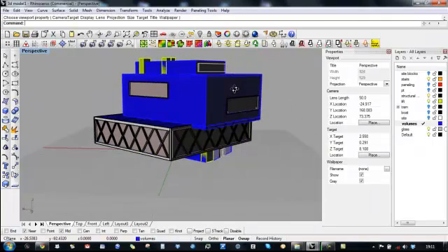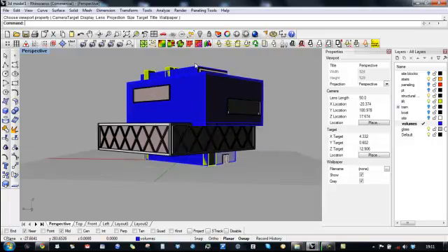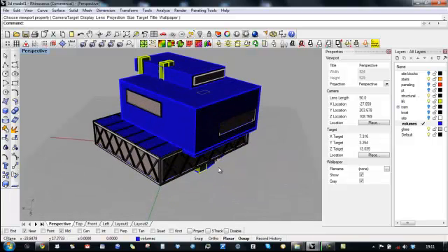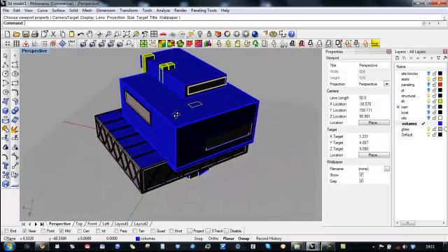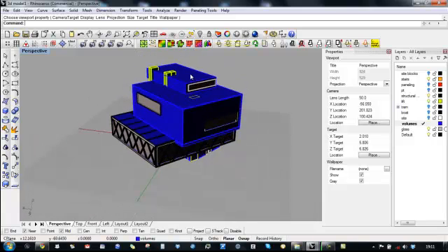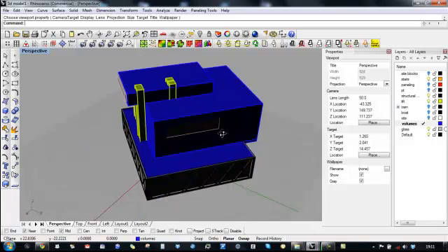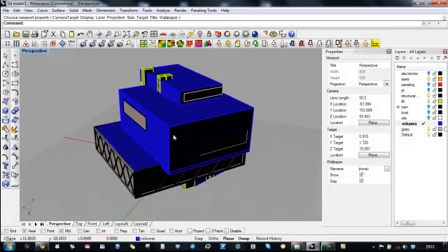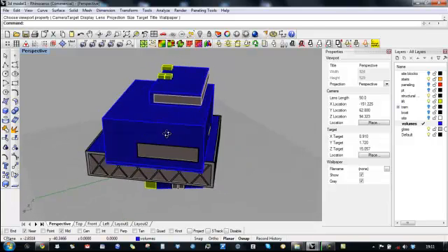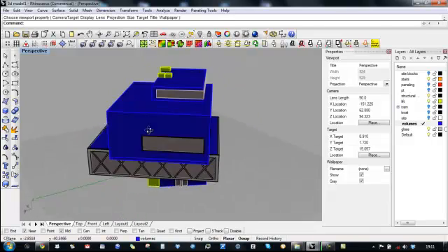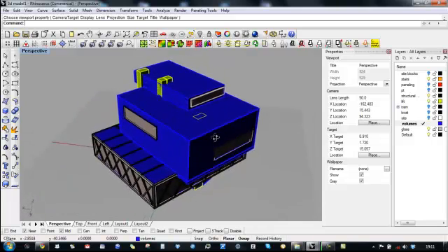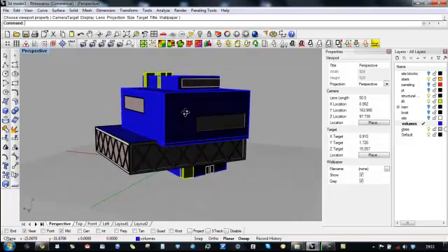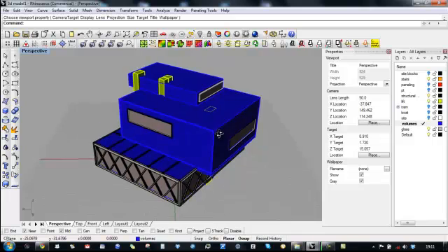It is important to include a certain amount of details in these models, so that when you then create the section to export it, it is easier to redraw this information. The process is not as straightforward as in other software like Revit or ArchiCAD, for instance, but for Rhino users, this is a way to go around the problem of having to draw sections and destroy the model to create them.